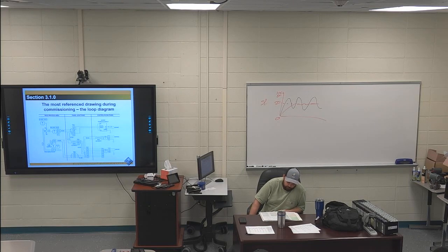The next bullet point, the whole thing is highlighted. Instrument index. This lists the instrument tag numbers for all instruments or control system components, including the associated drawing numbers, materials, specification sheets, and other related information for each component. A lot of highlights on these 2 pages.